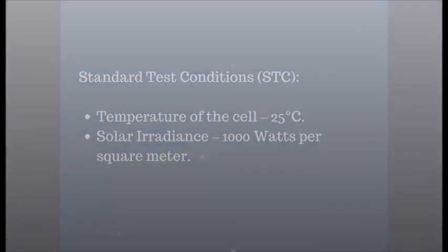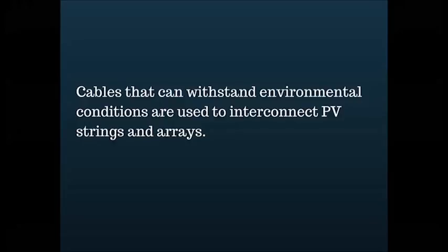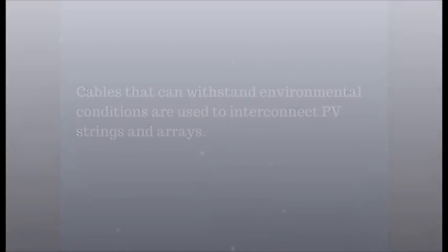Now, let's come to real world conditions. In real world conditions, PV modules are connected together in series making PV strings, and strings are connected together forming PV arrays. Particular attention should be given to the cables used for the connections. They must withstand environmental conditions.